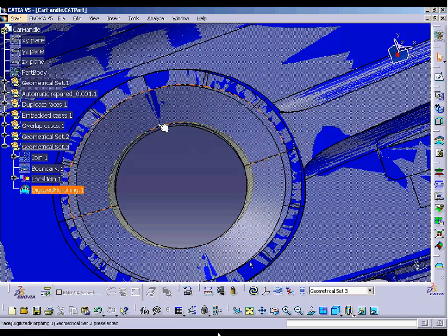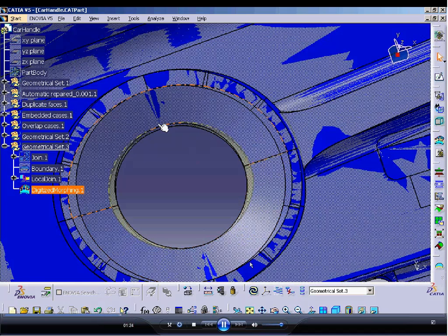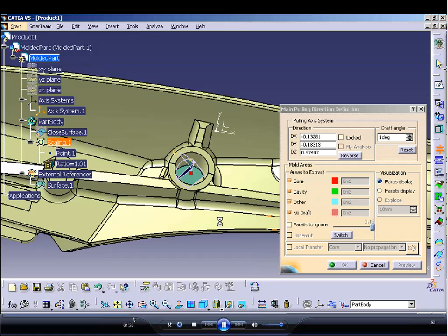So it's going to look like the wrong part, but when it comes out of the tool, it's going to be the right part. We do the same thing with spring back from stampings and so on. So instead of having to figure out how the stamping process is going to work, we're able to run this tool in order to morph this part. Very, very powerful tool in generating this.